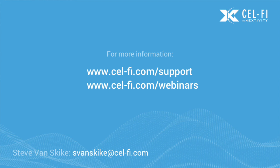They think they've opened up the firewall ports that are required for you, but they actually haven't. Those things happen. So we really recommend that you always show up with your own internet source so that you won't get slowed down by any of these site IT issues. Take an LTE modem, take a Wi-Fi extender and tether it to your phone. Do something like that so that you're assured an internet connection, and then you can quickly commission your systems.